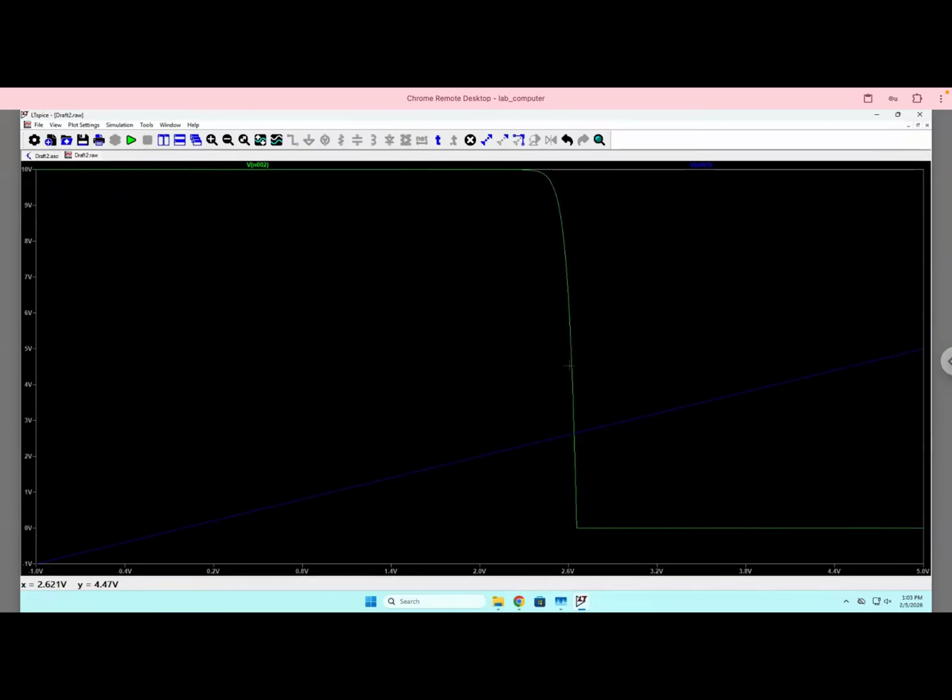And the way I'm looking at that is I'm literally just drawing a line in my head from 2.6 to roughly the middle of this line. Don't pick this MOSFET. This MOSFET sucks. Typically this slope would be a little bit more like this instead of exactly vertical, and it makes it a lot easier to eyeball it. I don't think we're gonna have a very smooth sinusoid with this thing, but that's okay.